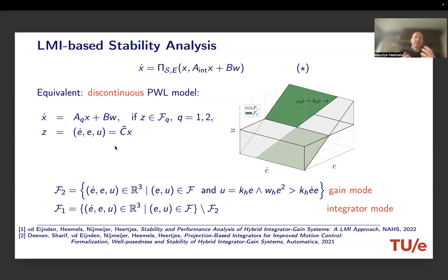Often what you see is that for piecewise linear systems, certainly in continuous time, the discontinuity can play a role. So you want to make sure you also have certain robustness properties, for instance, by considering Krasovsky regularization. That's one thing that's guaranteed by the result I'm going to give you on the next slide. But in particular, you have to incorporate that some of the linear dynamics, some of the modes, live on lower dimensional subspaces.